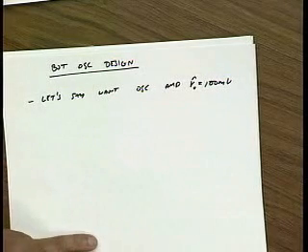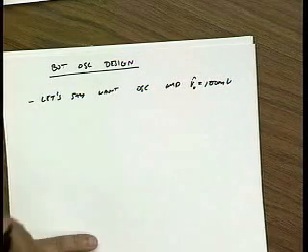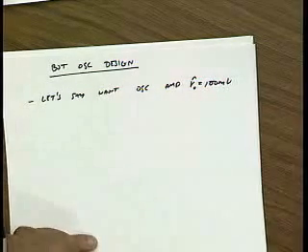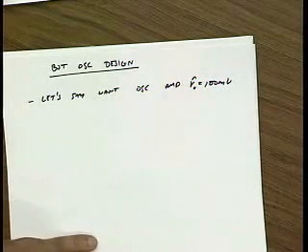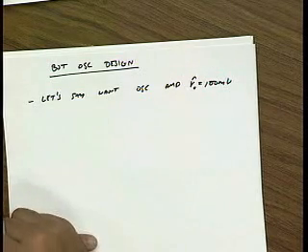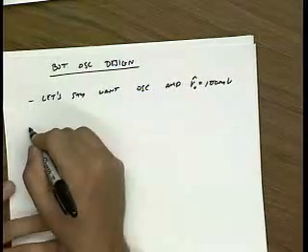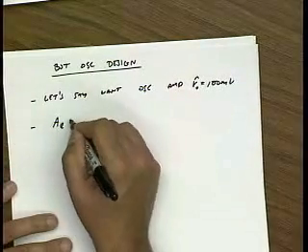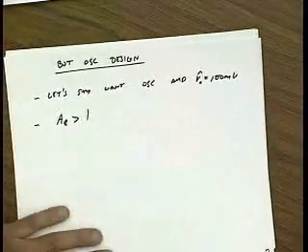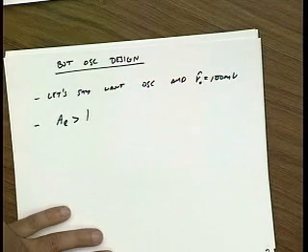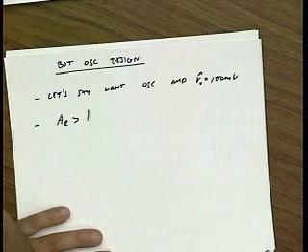You might say I have a VCO, I want a certain oscillation amplitude, I'm going to buffer it and then drive my mixers. And let's say you need 100 millivolts or a volt or 50 millivolts or whatever the case may be. Okay? So now the next thing that we choose, we know that we need a loop gain that's bigger than 1. So the question is, how much bigger than 1? 10, 15, 100, 1.1, 1.01, right?